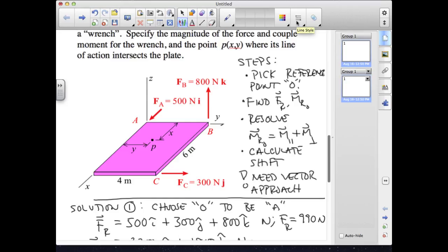So if I were to represent the resultant force and the parallel moment in this space, it's in the octant where x, y, and z are all positive. So this is my attempt to make my force vector come out at me from the screen, and the corresponding parallel moment component would be here. So here's our resultant force, and here's our parallel moment.